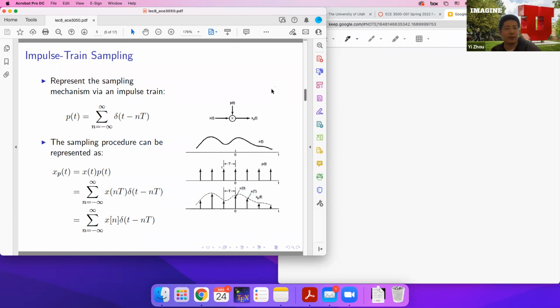And it turns out that the key is a concept called bandwidth that we introduced in the last lecture. As long as the underlying continuous time signal has a limited band in the frequency domain, we can always hope for a perfect recovery if we do the sampling fast enough.